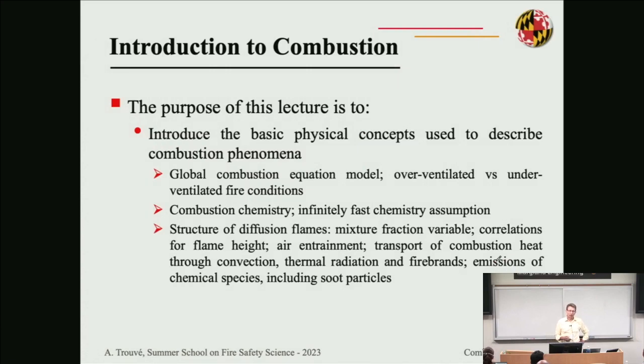To talk about combustion, you can go into great detail of chemistry, but in fact, we will not do that. I'm myself more of a heat transfer, fluid mechanics person, as far as combustion is concerned, rather than a chemical person. And I think this is also for good reason. We will use a global combustion equation model to describe the transformation of fuel and oxygen to combustion products, primarily carbon dioxide and water vapor. And when you get to that level, you have already 90% of the story of chemical change due to combustion. It is about right, and that's good enough for us in fire applications.